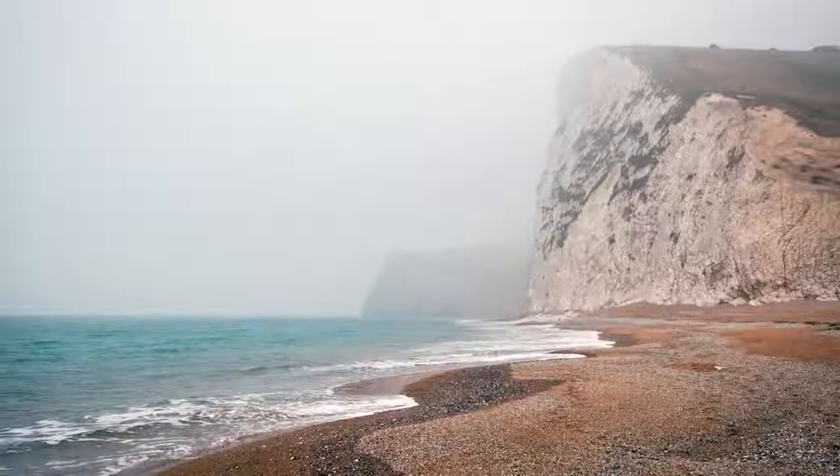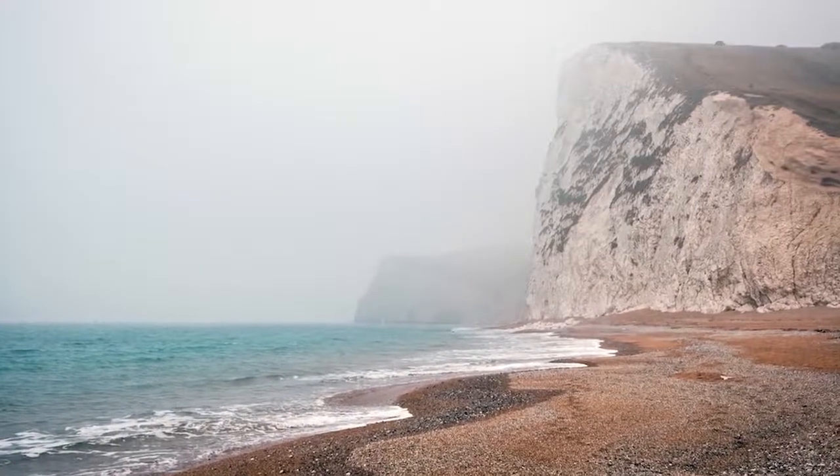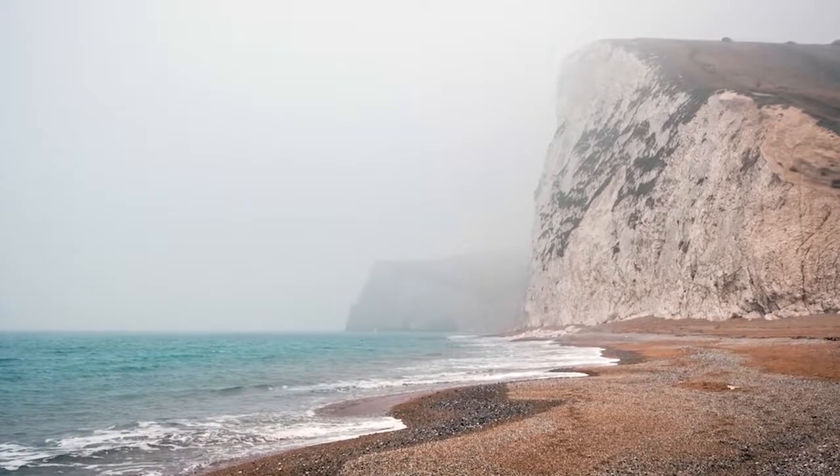Under diffuse cloudy conditions, global sunlight is dominated by the indirect factor and spread more evenly across the sky. Angling the collector away from due south actually limits the amount of available indirect light, and there's a negligible amount of direct sunlight that's available.